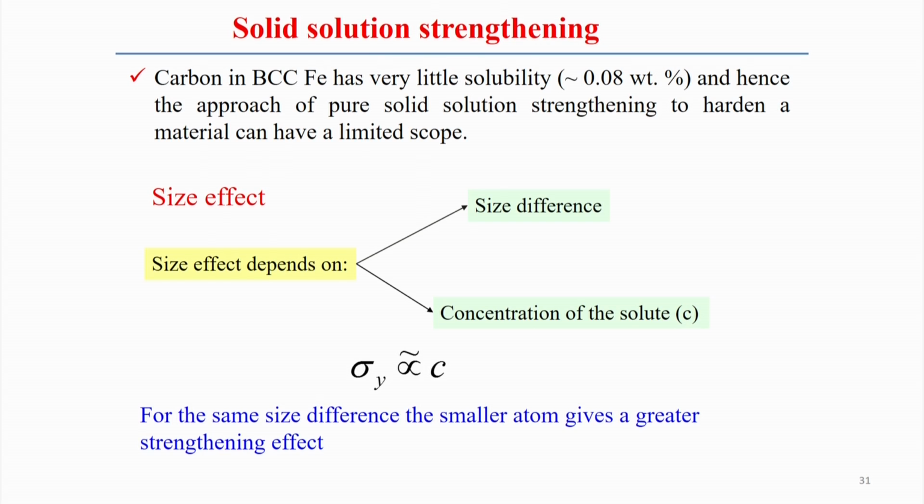Now what are the other factors? The size effect depends primarily on the size differences in the solution, and the other is the concentration of the solute. These two are the most important factors that finally affect the hardening mechanism in a solid solution. The yield strength of the solid solution is almost proportional to the concentration of the solute, so the difference in sizes is rather less important here.